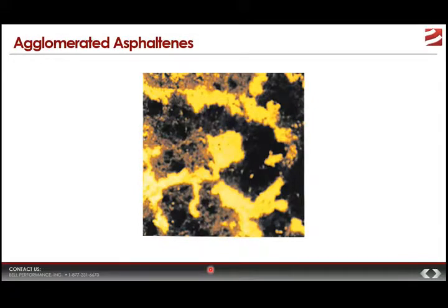When they undergo certain kinds of reactions, they might react with paraffins under high temperatures, and they become unstable. That state becomes broken down. Now, once the protective micelle structure has been broken, the polar asphaltenes, the asphaltene molecules that have positive or negative charges, will tend to seek each other out, and they will start to agglomerate together. And then that enables them to travel to metal surfaces and tube walls and things like that. And that's when they form these foulant layers that start to cause problems in these systems.